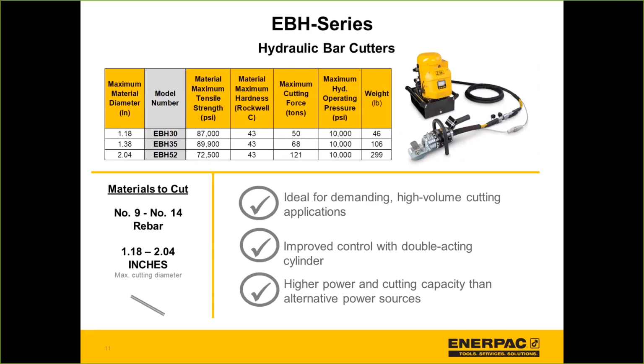And where are we going to be using these hydraulic tools? We're going to be using these tools in those applications where you're either going to need a bit more power, or you've got a larger application, or you've got an application where you're really going to be doing a high volume of cutting, because in this case we're using an external pump with a large reservoir with a lot of hydraulic fluid, which means it is not going to get hot very quickly at all, which means you can just keep using that tool for longer periods of time.